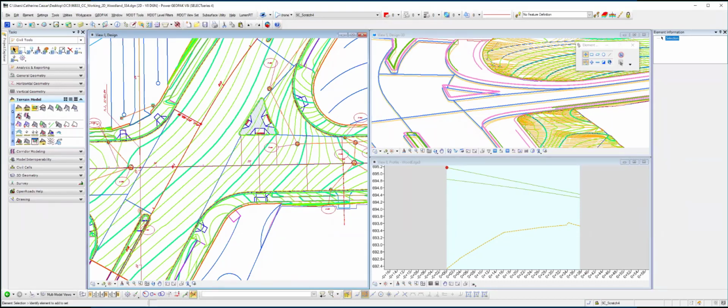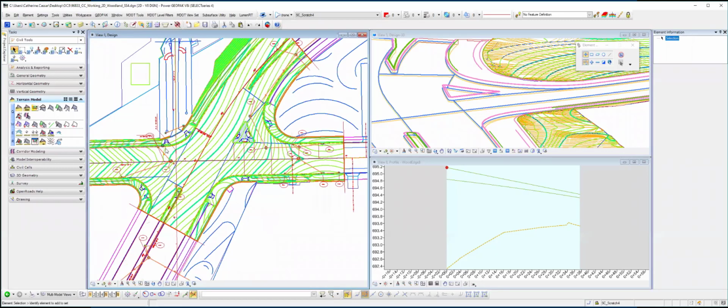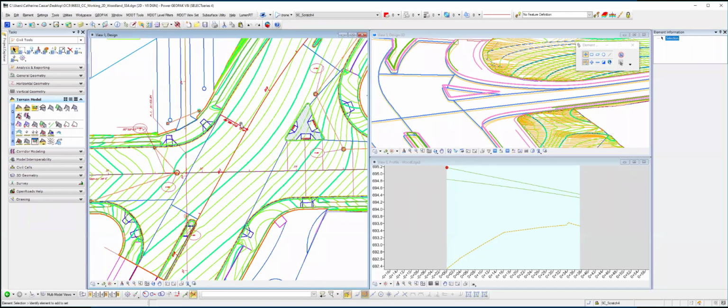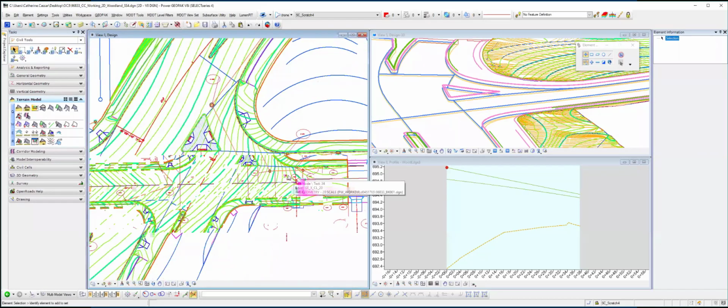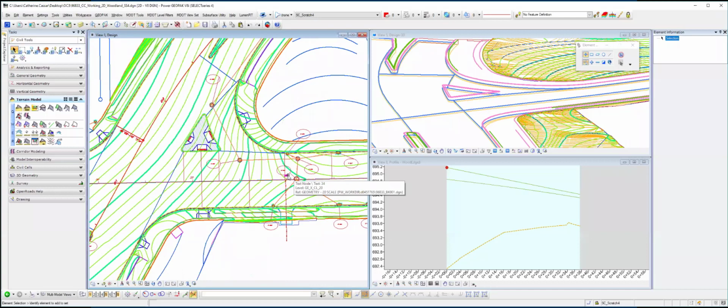So anyway, this is challenging because you've got the catch basin locations you're tying into, the low points you've got to get, sidewalk ramps, all those things come in. This one was extremely complex. You notice I had all these sidewalk ramps that I had to make sure I was no more than 2% slope across any of them, and across the pavement at the location too. So it was a pretty interesting project to work on, this particular portion of it.